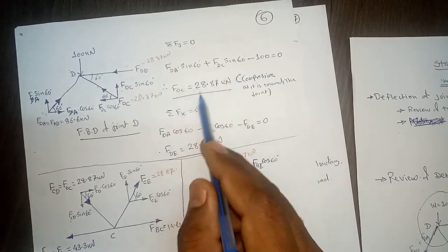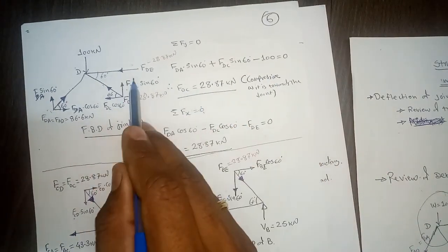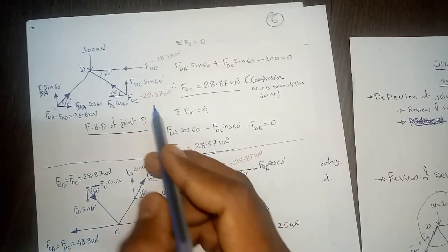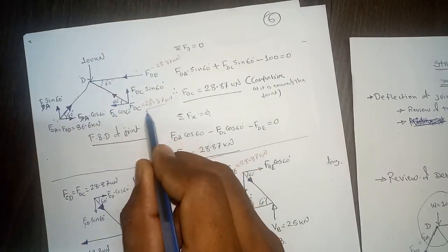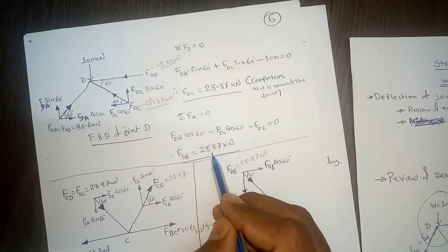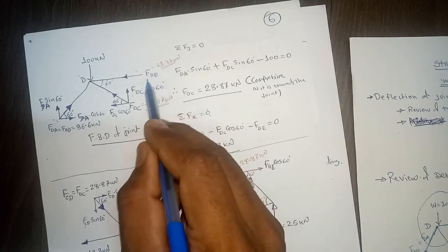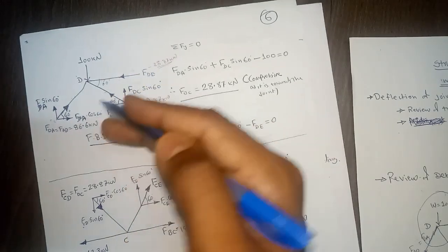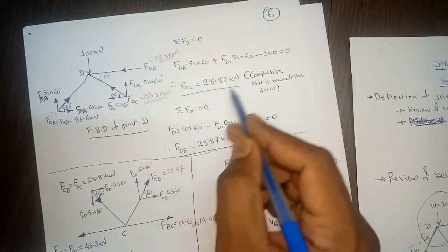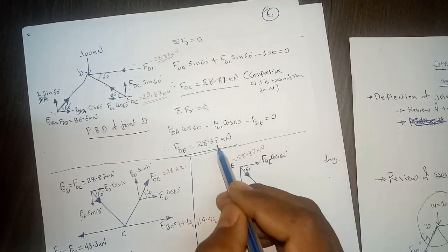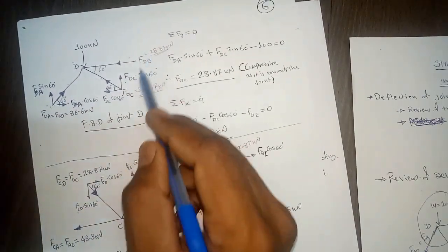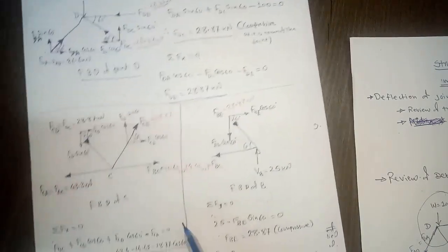So if you solve that, you will get the force in these two members, DE and DC. Again, as a standard practice, always write down the numbers you get in the calculation in the figure. Why? Because if you solve more joints, it is difficult to keep checking those numbers in the calculation. So have a practice of mentioning them in the figure, where it is easy to observe those numbers.